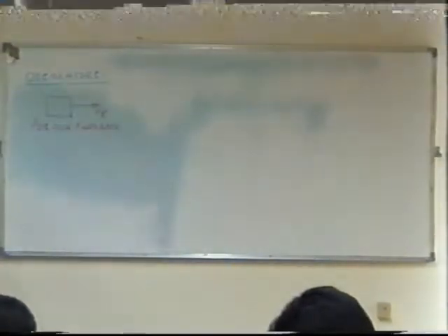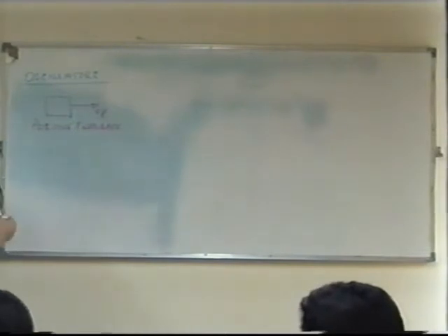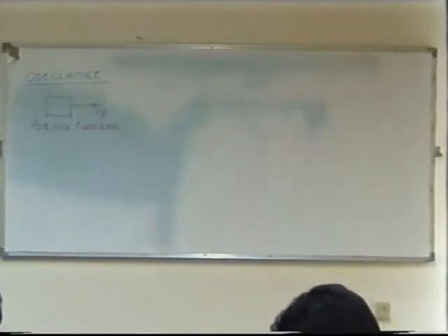Secondly, there must be something in the circuit that's going to determine at what frequency the oscillator is going to oscillate. So there must be some circuit, part of the oscillator circuit, that determines the frequency. For example, we could use an inductor and capacitor in parallel, which is a tuned circuit. Yes, that's quite a common type of oscillator.